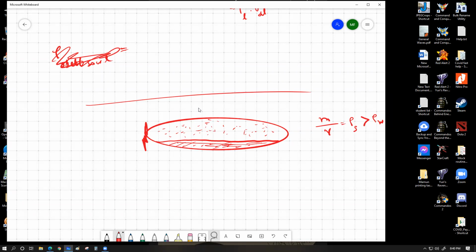If you fill up this thing with more crew, then your crew actually provides a significant amount of mass, so that you don't have to fill up the ballast tanks completely, which gives you a bit more advantage. So that's how the submarine works, because whenever it is underwater, the total volume of water that the submarine displaces is fixed, equal to the outer shell volume of the submarine. The key thing that the submarine changes is the amount of mass within itself. Whenever it pumps water in, it increases its mass.